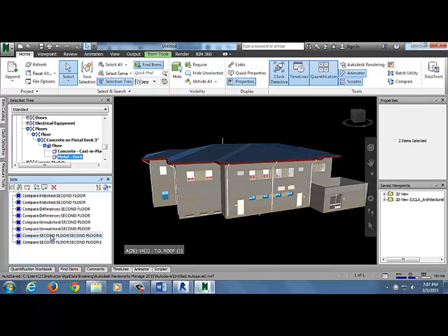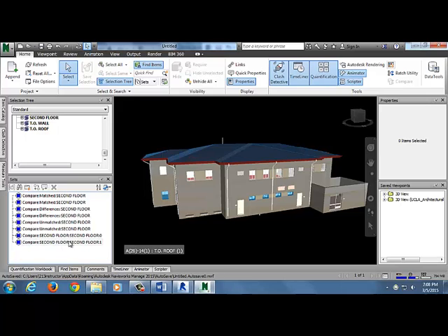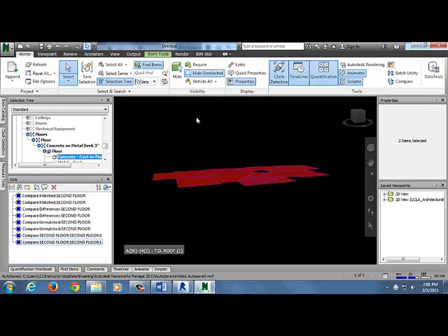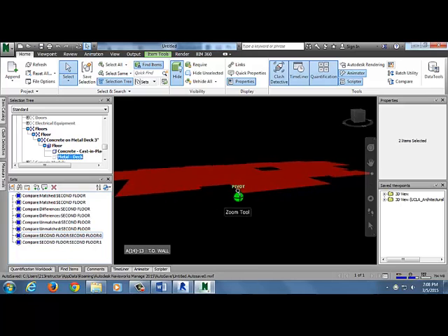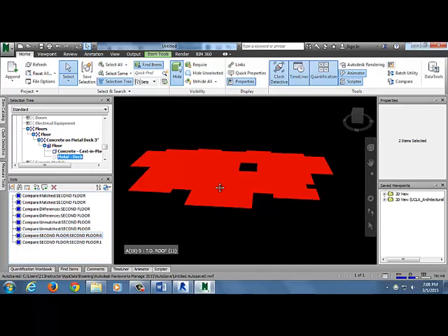Second floor. So first it does those pairs, right? Two matched, two differences, two unmatched. And then because I said do each difference as a set, it's going to show me just those items that changed in geometry. So I can see this one. So I'm going to show both of these. I can see those are the only items that changed on the second floor, apparently, from that level two.